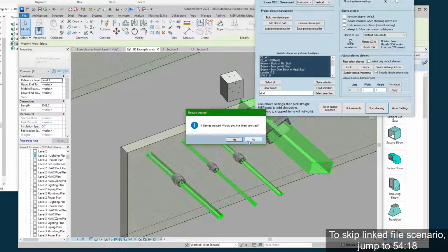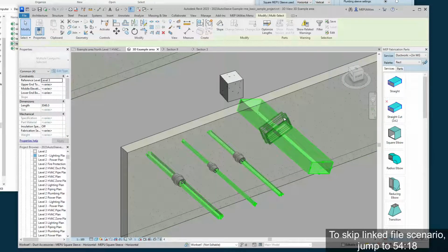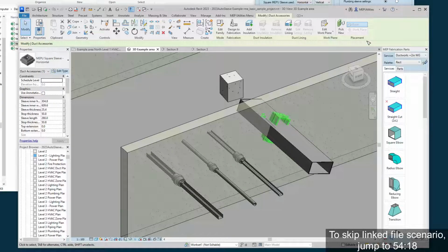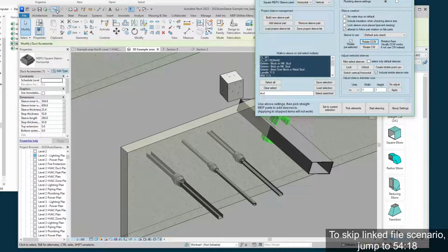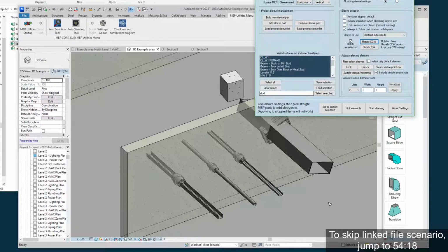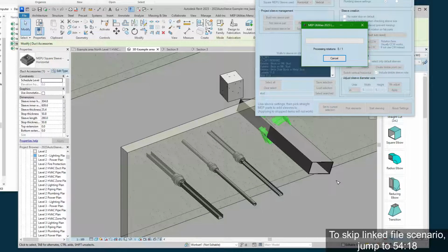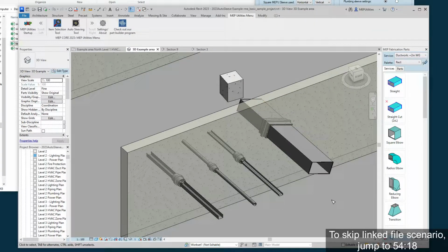And there you go. And as you can see, this sleeve got placed incorrectly, so we'll just grab that one, pre-select, and we will rotate counterclockwise. Nope, that's the wrong direction. I'm surprised. All of these are usually counterclockwise. It's rare to have it go clockwise. Just inconvenient situation, I guess. But either way, as you can see, the duct has been sleeved correctly, the pipe has been sleeved,